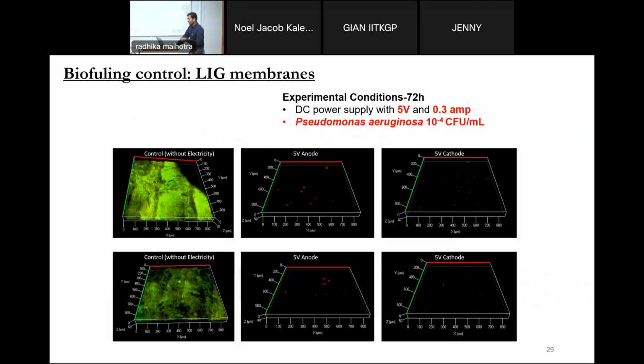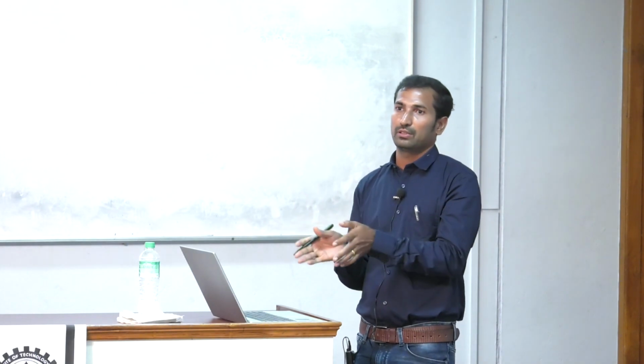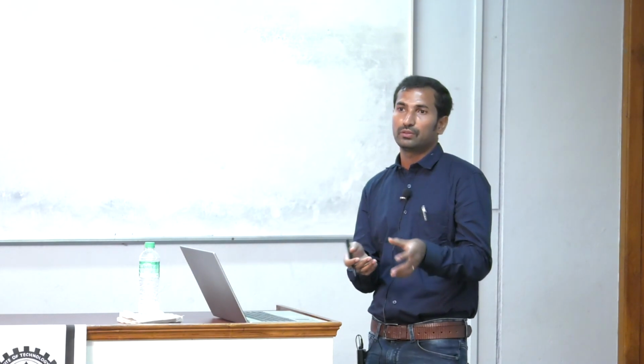In addition, in this work we have checked the biofouling formation also. In membrane distillation, most people do not talk about biofouling, but still there is a problem. So, for this purpose again we applied electricity, especially for the biofouling experiment, and we observed a similar trend to what we got with the previous works with pressure driven membranes.